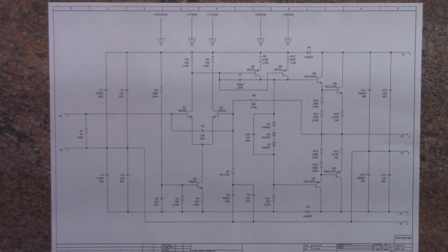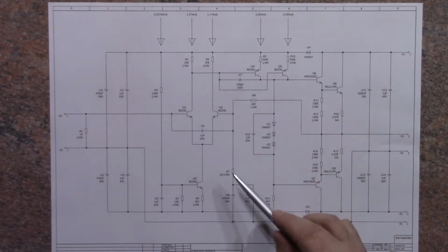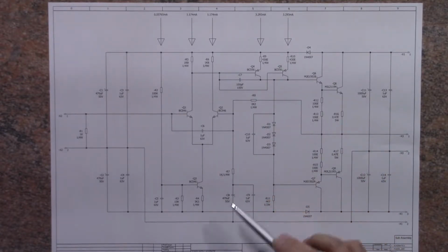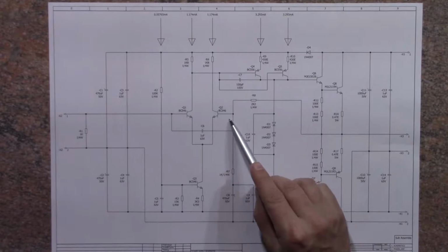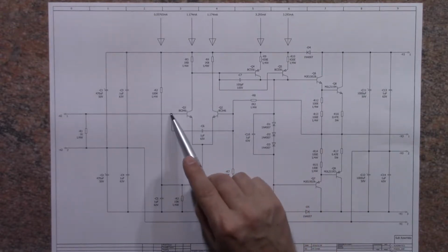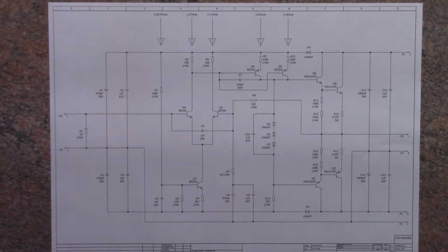The power amplifier is essentially an operational amplifier built from discrete components, and in particular it's set up to work as a non-inverting amplifier, and the gain is set by this resistor divided by this resistor plus 1. Simply put, it looks at the current on this transistor over here and the current on this transistor over here, and it tries to balance the two.